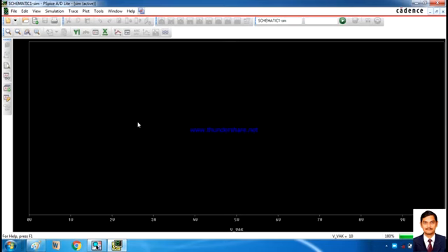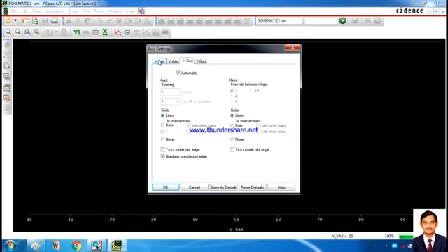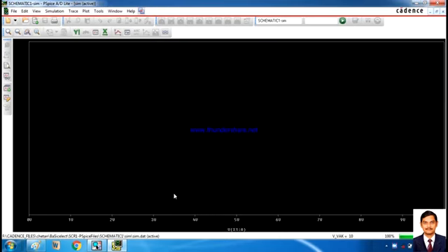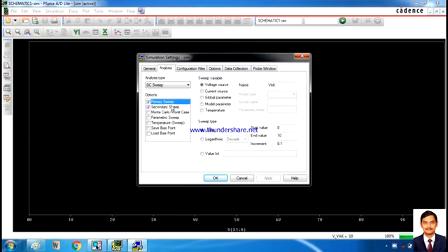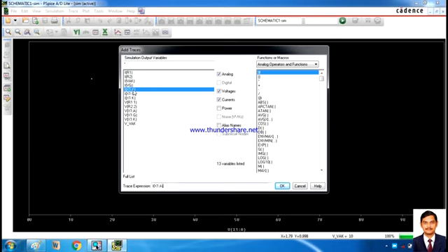The x-axis parameter I require is VA. In order to change that, I have to go to the settings, go to the x-axis, go to the axis variable. Then I have to find this particular anode voltage. So I got an axis here, 0 to 10 volts. I have already applied the variations here. In Simulation, Edit Profile, you can observe that the primary sweep is VAK, varied in this extent, and the secondary sweep is the gate voltage, with start value 0, end value 5, and increment 0.1. On the y-axis I require the anode current. This trace expression is written here and plotted here.